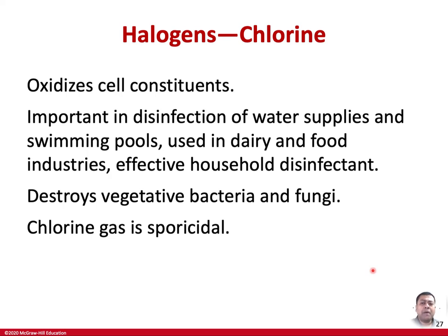Almost all microorganisms are killed within 30 minutes, but there are two eukaryotic pathogens, and unfortunately both of them are waterborne. One is Cryptosporidium and the other is Giardia. Cryptosporidium causes gastrointestinal disorder. Giardia does the same, known as giardiasis. These are not killed by chlorine. So that's a problem.